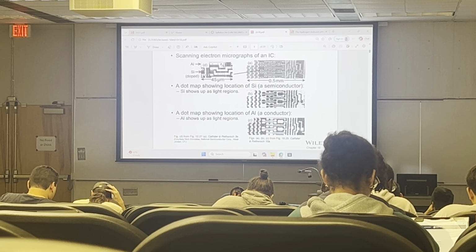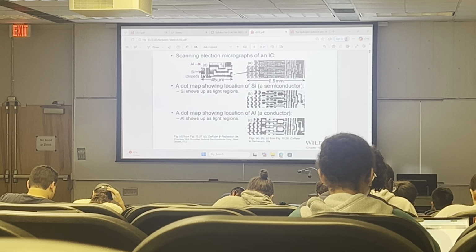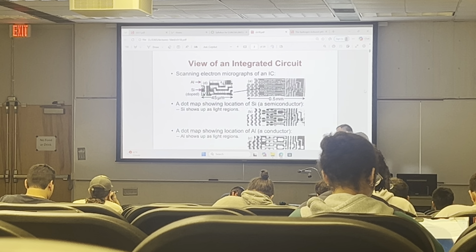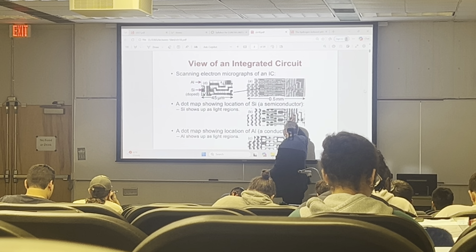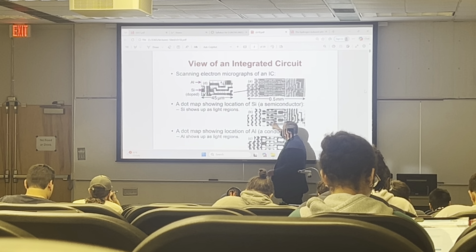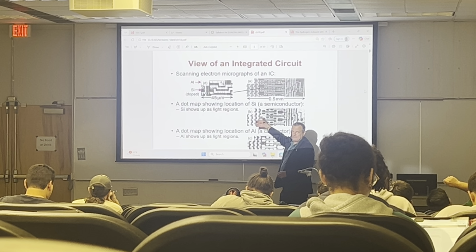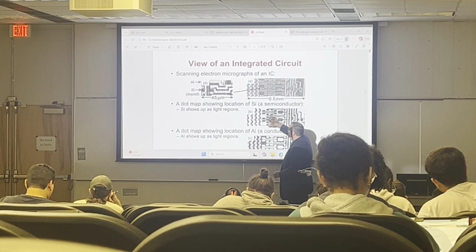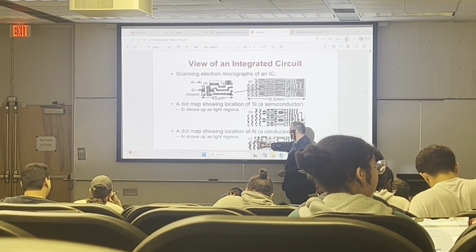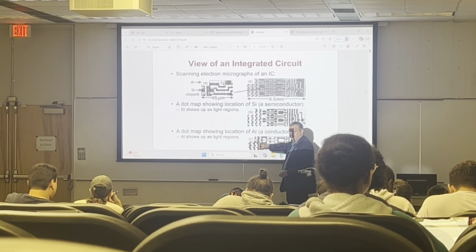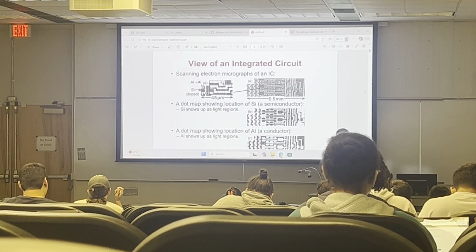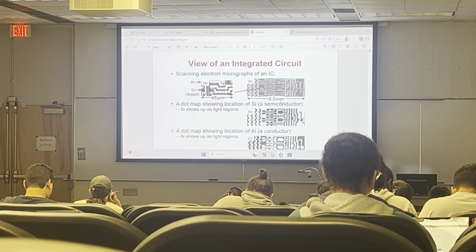And there's a process called EDS mapping, energy dispersive spectra, because each material has a certain energy associated with it, and when the electron beam is rastered like this very fast, you can collect the X-rays, and that X-ray signal would give you the specifics. So what you see here are the light regions, that's the silicon region, and you can see here the light regions are the aluminum. So we do have characterization techniques. That's how it looks like under the microscope. And this is a 0.5 millimeter scale bar.